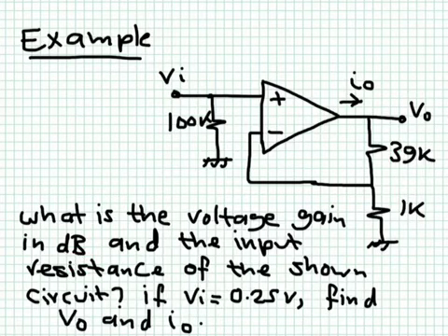Now, what is the input resistance seen? The input resistance is simply equal to this 100K in parallel with infinity, because the resistance seen looking into the op-amp is infinity. So the input resistance seen in this case is not really infinity, it is equal to 100K. Why would I put a 100K like this one? Maybe there is a capacitor in the previous stage that needs to discharge. So this 100K would allow such a capacitor discharge. So this may be one possibility for having something like this.